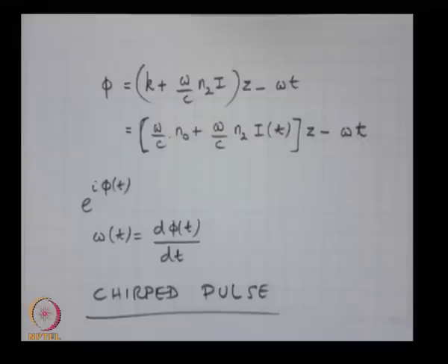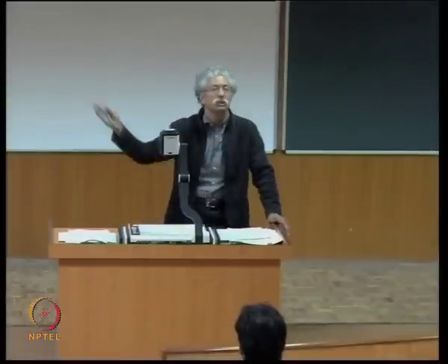The frequency within the pulse changes with time. This term comes from bird calls which chirp. The birds chirp, so there is a frequency which varies with time. And that is essentially a situation where the frequency of the signal is not constant within the pulse, but changes with time. In general, in any pulse, we say that there are multiple frequencies present in any finite duration pulse.